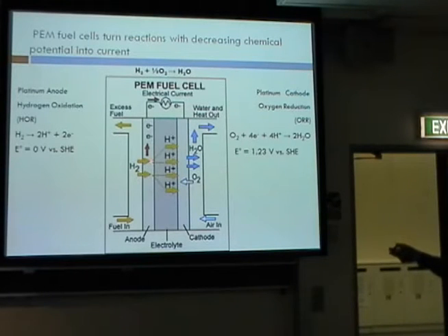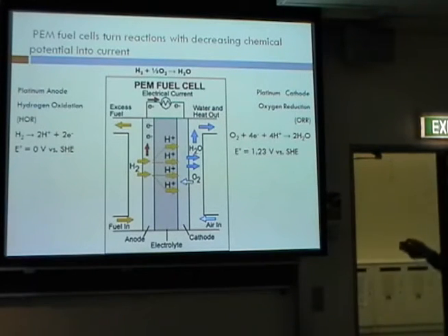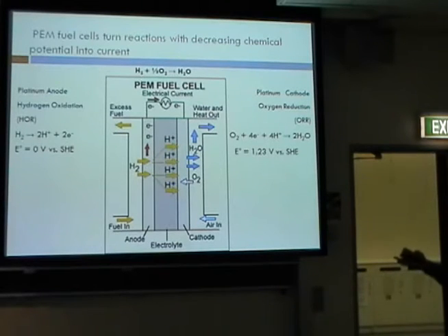In this case of a PEM fuel cell, the protons actually go through this electrolyte material, which is typically a solid polymeric electrolyte. So Nafion is the most common one used today. It basically promotes acidic transport across this membrane, but the membranes are electrically insulating, which is why the electrons flow through the external circuit. The electrons then recombine with the protons and oxygen that's coming from your airstream that's being fed in order to do this reaction, which makes water.